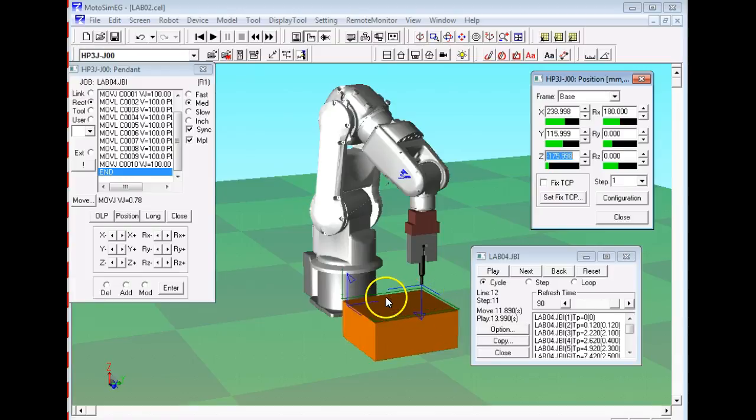You have to make this model perfect. So you'd get your model or whatever you're doing, and you would measure it, right? You might measure it with a set of micrometers, which are extremely accurate measurement devices, and you would go in and measure all the dimensions of your workpiece. And then you would create a model. So this is a created model. The model for the robot, you import that.